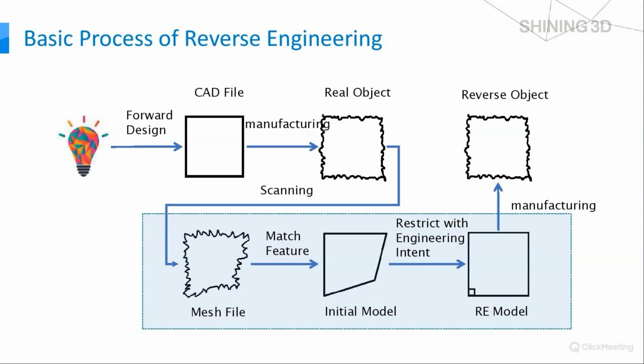And if you scan it, first, the top and bottom surfaces are not perfectly flat. Second, the top and bottom surfaces may not even be parallel. However, when you are doing reverse engineering and drawing the CAD file of your cell phone, you know that the top and bottom surfaces of your cell phone have to be parallel, right? When someone designed it, they designed it as parallel. Otherwise, it would not be a box.